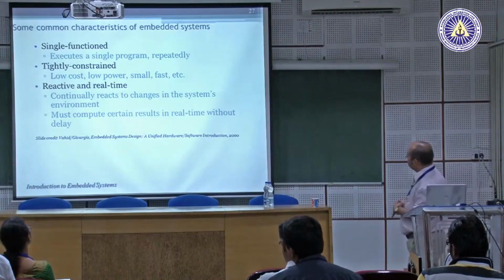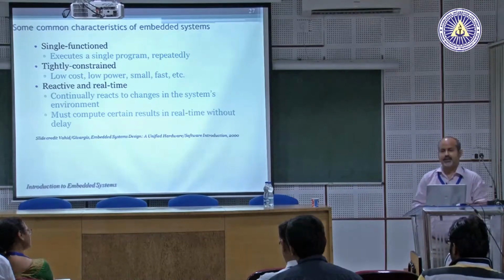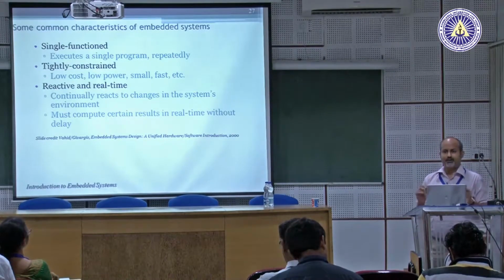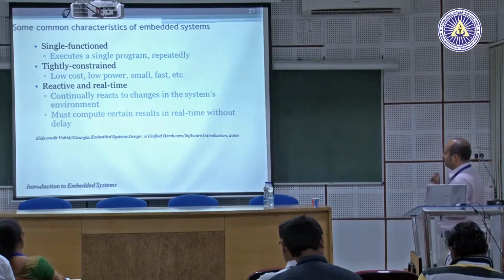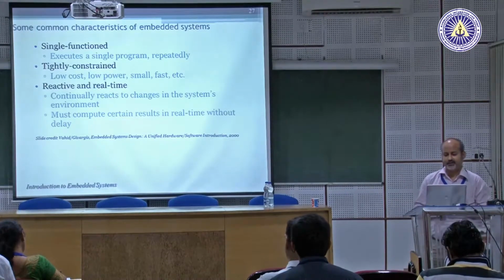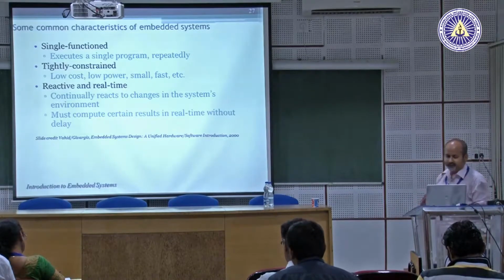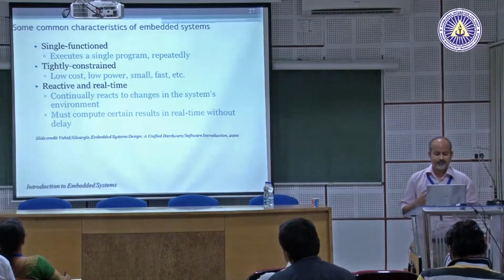Normally these embedded systems are tightly constrained in the sense that the cost has to be very, very low, the power consumption has to be very low, and the form factor must be small so it fits in various places. It has to be fast enough to actually provide the service that you require of it.